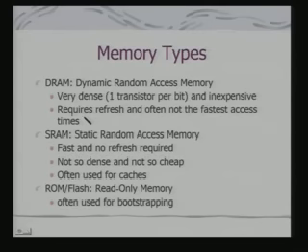In fact, dynamic random access memory is very dense and consequently inexpensive, but it requires refresh. Why it requires refresh, we shall understand when we look at its structure. Static random access memory is fast, no refresh is required, but it is not as dense as dynamic random access memory, and often it is used for cache or other applications where we require really fast memory.